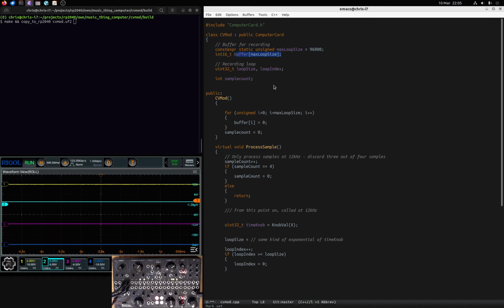So I don't want really long lookup tables. What I would rather do is generate a shorter lookup table and interpolate between those entries linearly. That linear interpolation should be good enough for this purpose when this isn't directly controlling pitch or anything. And that will allow me to have relatively few entries in the lookup table.